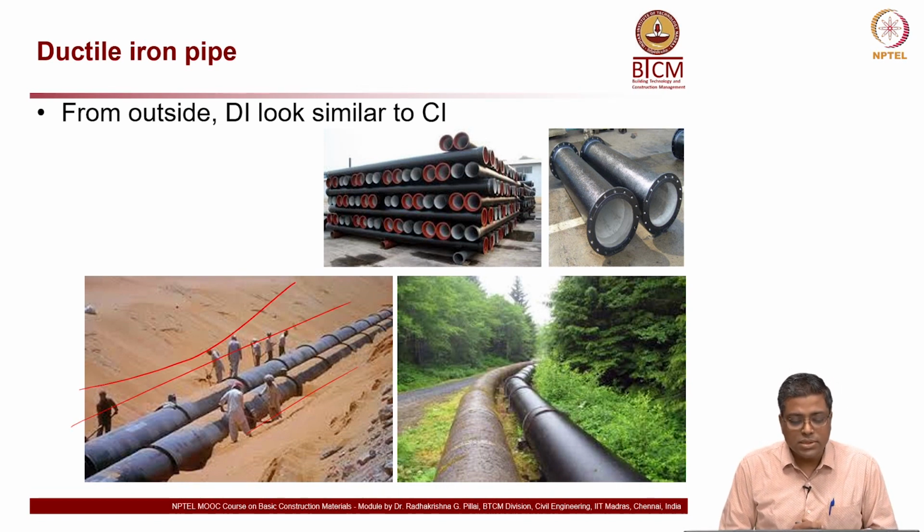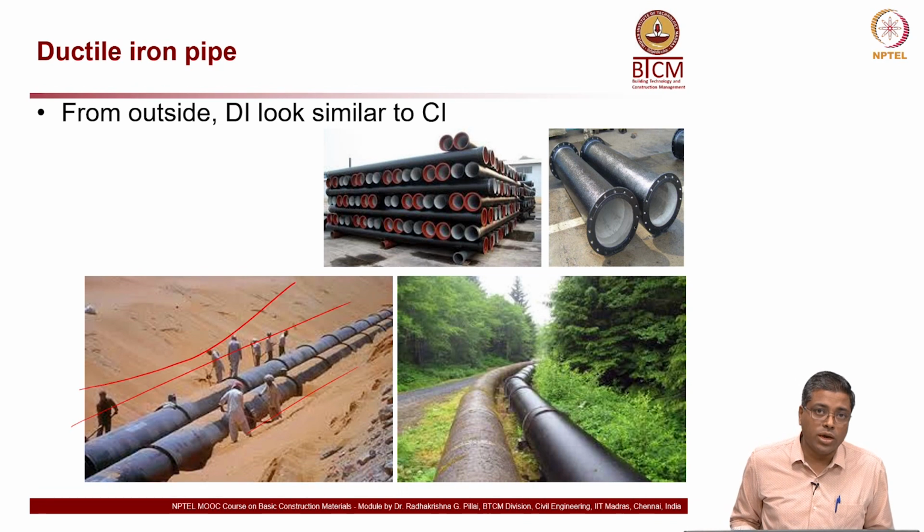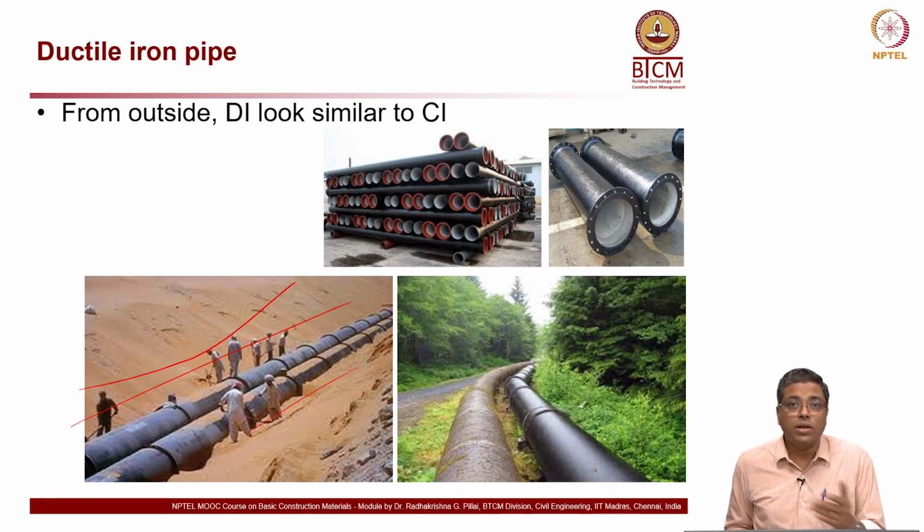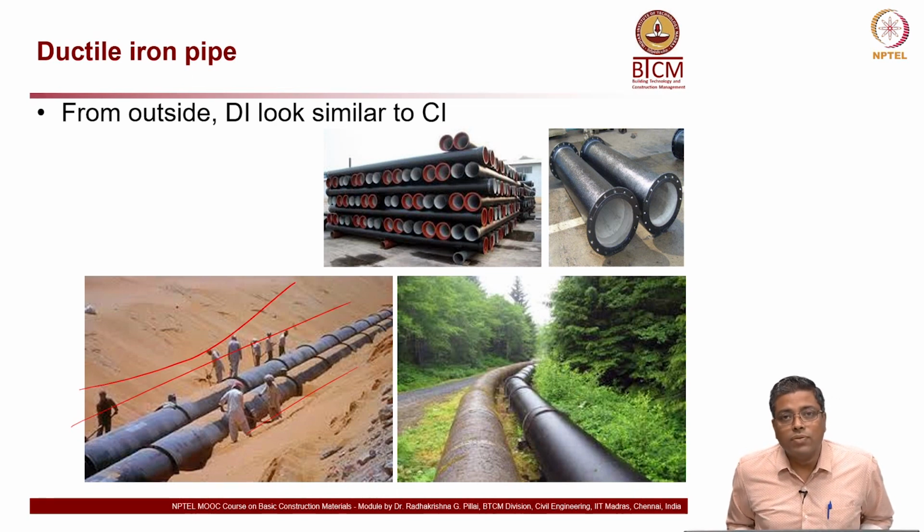So, nowadays you will see that ductile iron is more preferred than cast iron products, especially when you talk about possibilities of deformations. Okay, and you want structural systems like even these pipes to deform but not crack. Okay, so that is the idea. Deformation is okay, but it should not crack, because if it is cracked, the liquid which is flowing through will leak. So, that we do not want to happen. So, we want ductile structures and we do not want structures to be very brittle in nature.